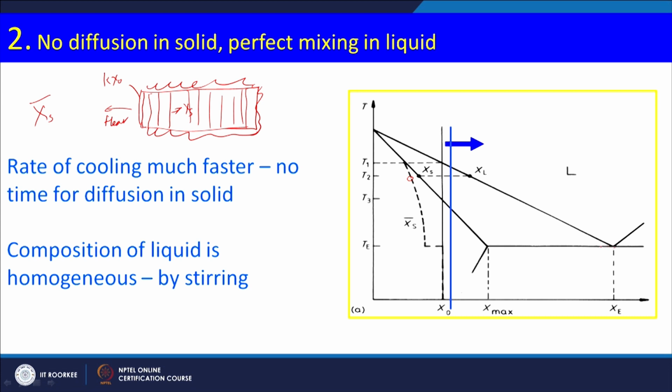So, always in a non-equilibrium condition, though under equilibrium condition it is not going to show any eutectic because it is in single phase, because of the non-equilibrium cooling I am always going to get some eutectic mixture in the material. A very important thing is there to remember.